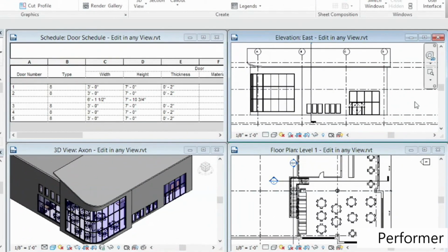Okay, so let's look at a really simple example. I can see here that I've got this really big blank wall here in the east elevation. You can see it also here in the 3D view. It wouldn't really be very easy to do something about that from the floor plan that I currently have open, but there's no reason why I can't do something about that using the elevation. So what I'm going to do is click here to the left of the last window and drag to the right. Now, the one thing you've got to notice here is it's highlighting a bunch of stuff beyond.